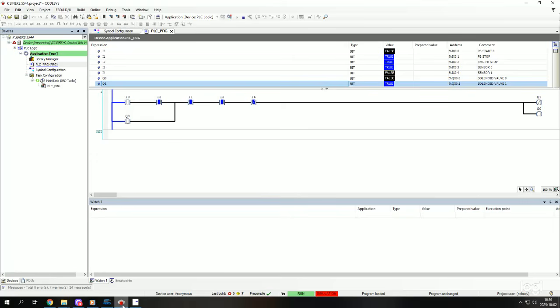So exercise 5, what we've built now, having 2 sensors, that's exercise 5. It reads as follows. Bottles need to be diverted in groups of 3 from one conveyor to another by means of a diverter. After being switched on, the system should run continuously. It should not be switched off until a stop signal is generated. The sequence is started by pressing a push button.